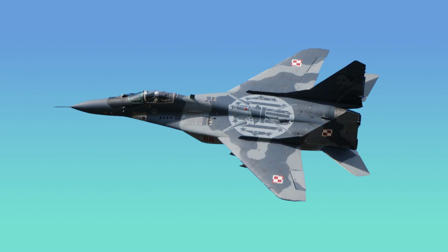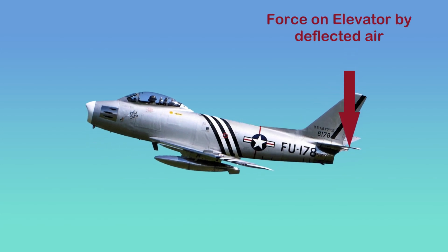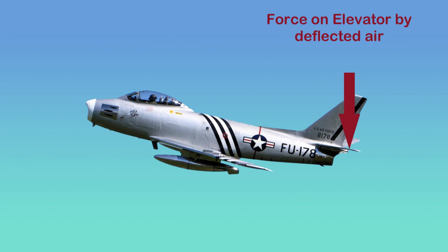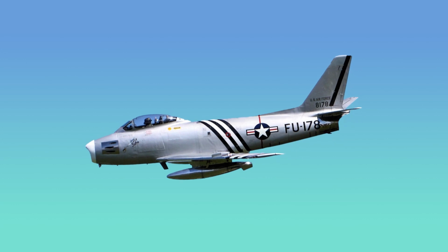Then the nose-up movement of the aircraft, or the pitch. It is to move the aircraft around its horizontal axis. To do this, here is the elevator. When the elevator moves this way, the airstream will be diverted up and the airstream will push the aircraft's rear fuselage downward, and it will make the aircraft move about its horizontal axis. And to make the nose-down movement, the elevator has to move in the opposite direction.